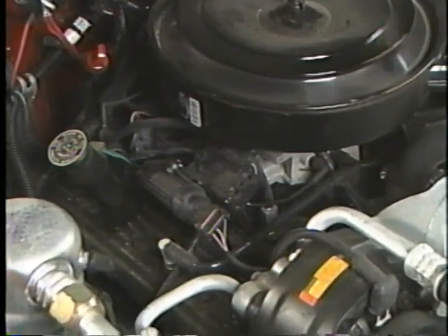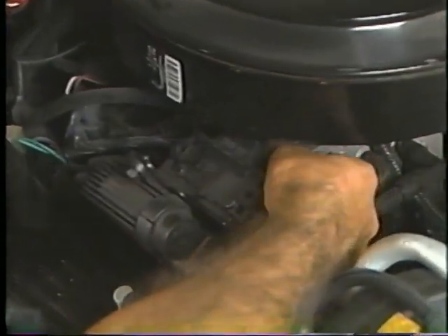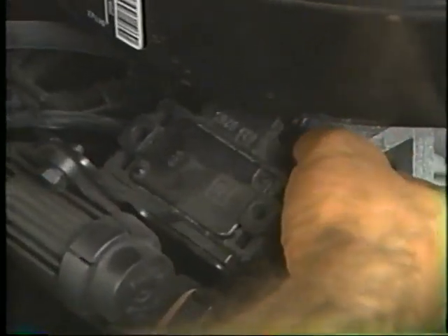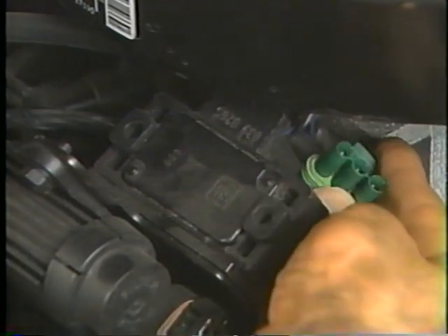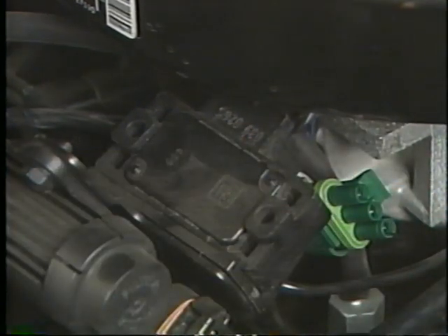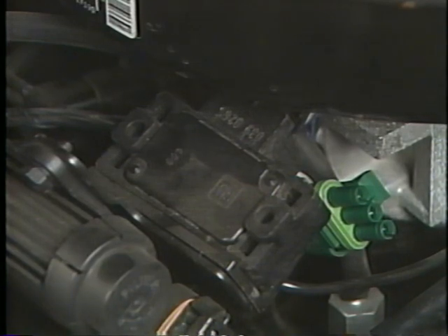unstable idle. If you have a misfire or bad idle condition, try disconnecting the MAP sensor. With the sensor disconnected, the PCM uses a default MAP value and controls fuel delivery based mainly on TPS signals and engine RPM. If disconnecting the sensor makes the engine run better, troubleshoot the sensor. If it doesn't, troubleshoot the misfire or idle condition.